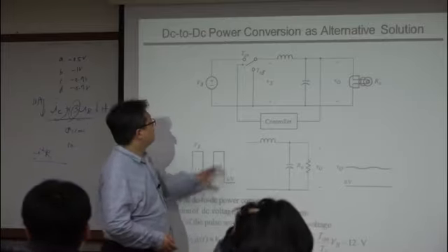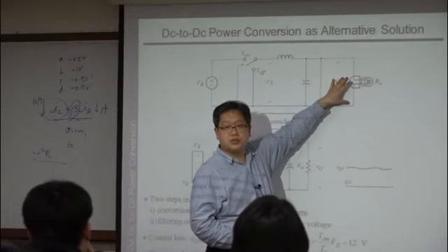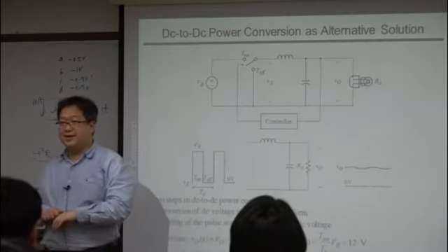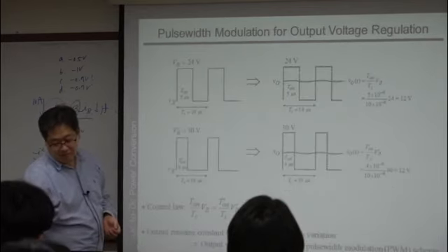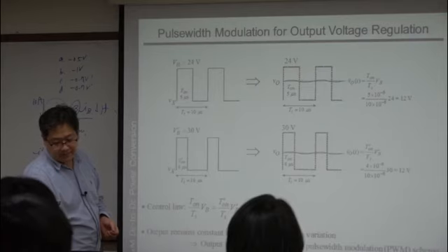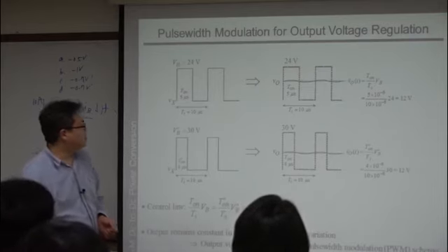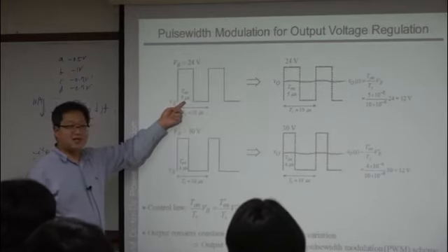Then, your input voltage is high, output voltage is low. Buck boost or buck? Which one? Buck, right? A simple buck converter. You can also easily adjust your output voltage by changing the duty cycle.